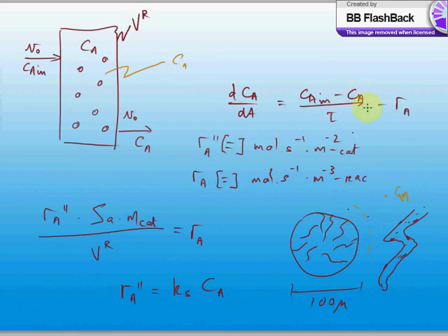We can't say that this concentration in our rate expression is the same as the concentration in the fluid here. So we actually need the particle's concentration. So let's amend this notation. Let's say Ca over bar is the average concentration inside the particle. So there exists some average concentration in this particle that we have to determine before we can solve our reactor balance.